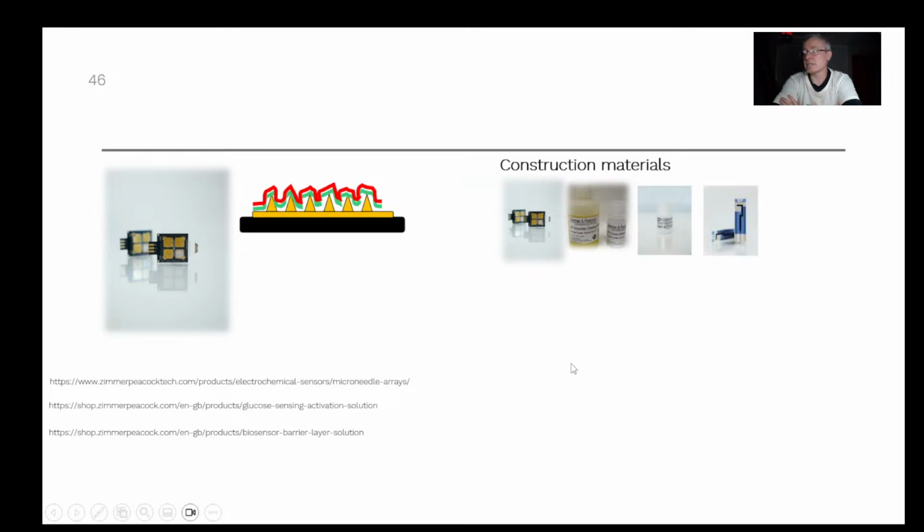Now, what I would say is those microneedles are quite expensive. I would say practice on screen printed electrodes, on our platinum hyper-value screen printed electrodes, because then you can afford to make mistakes. If you can get it working on the screen printed electrode, then you're ready to translate onto the microneedles. Otherwise, you're doing your development or functionalization on the microneedle, and that could be a very expensive platform if you make mistakes on it. So I'd actually practice on the screen printed electrode.